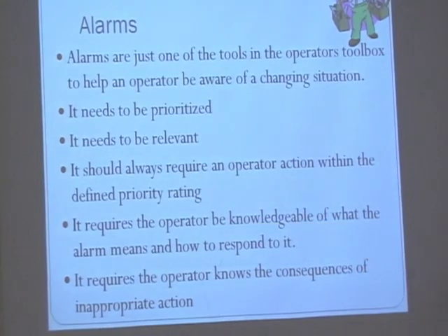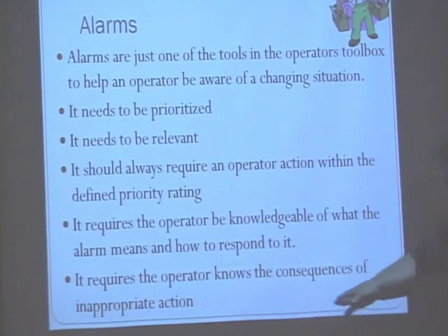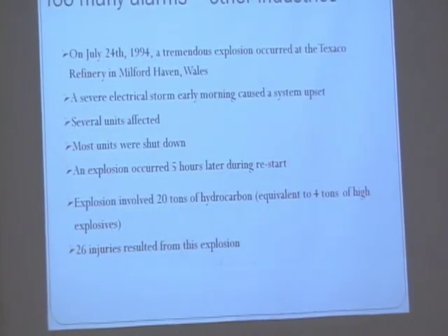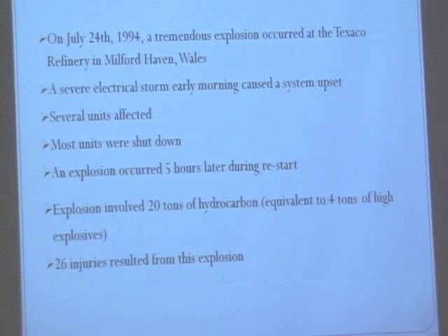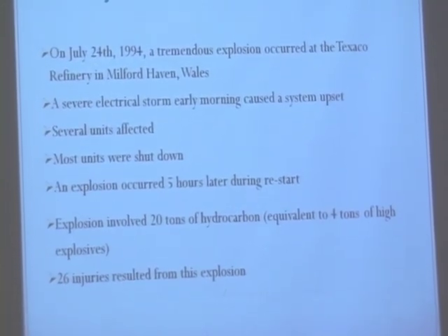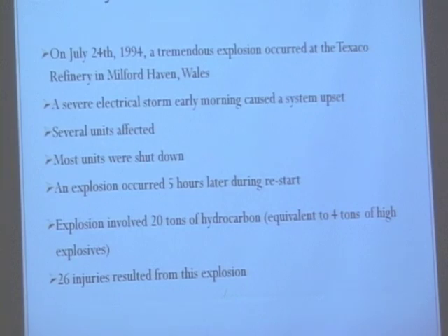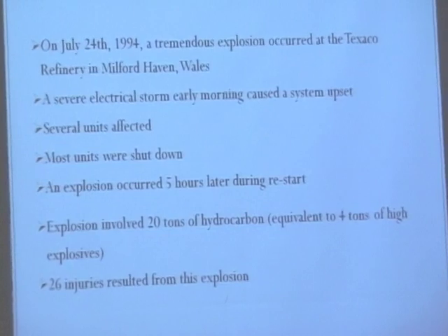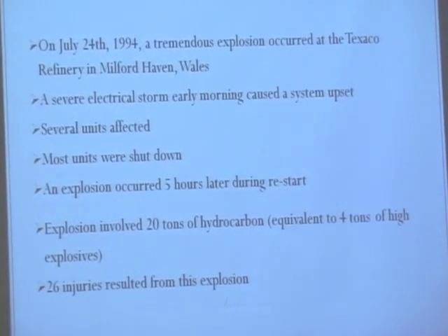It requires the operator to be knowledgeable of what the alarm is and how to respond to it. And often we don't always have that. It requires the operator to know what the consequences are of not responding to that alarm. And what you'll find is that it's not documented. It should be documented. That's the first thing that should be documented on every alarm system: why the alarm exists, what's the appropriate action for that alarm, and what are the consequences of inappropriate action. And you should be able to look that up on any alarm that comes on the system.